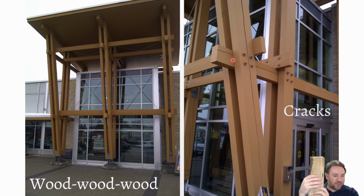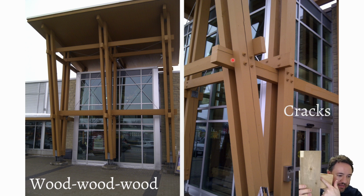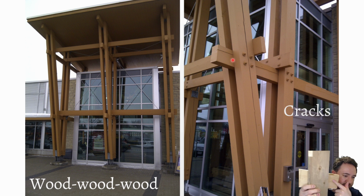Okay, so let's say that I have these 2 wood members connected together. And this is a problem also in steel connections. I have these 2 wood members connected together, and this one in the back does not want to shrink in this direction. So along this entire length, it doesn't shrink, or only a very small amount, because it's longitudinal to grain shrinkage. But this member does want to shrink. If I put 2 bolts here connecting these 2 members, this wood member wants to shrink if it gets dry, and it wants to expand if it gets wet, right? So moisture content is going to cause this to shrink and expand.